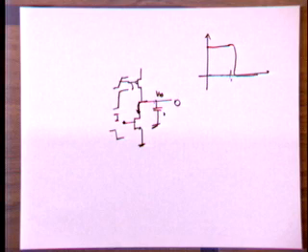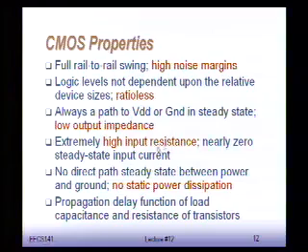So the other nice thing about CMOS gates is that they have a high input resistance. All gates that you build in CMOS have it, regardless of how you do it. And also, they have no static power dissipation, okay? Usually this no static power dissipation is pretty much related to being ratioless. If a family is ratioed, usually it also has static power dissipation. This is the case, for example, for pseudo MOS and for RTL. So being ratioless and not having static power dissipation are kind of related, although they're not really the same thing.